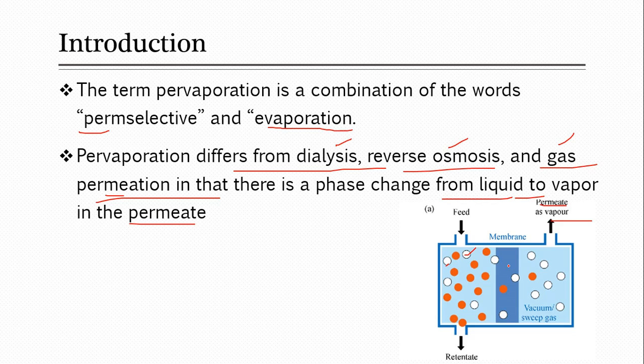So here, when some species pass through this membrane and are converted into vapors inside the membrane, their diffusion will increase, and when diffusion increases, definitely their separation is higher compared to other components, which diffuse slowly. Overall, with this you are increasing the rate of diffusion and the rate of separation when you use the pervaporation selective membrane. Hopefully it's clear to you.